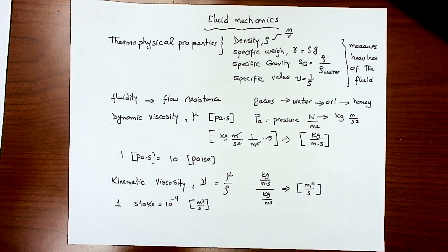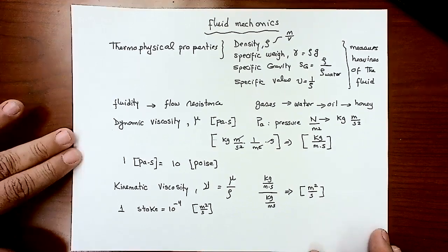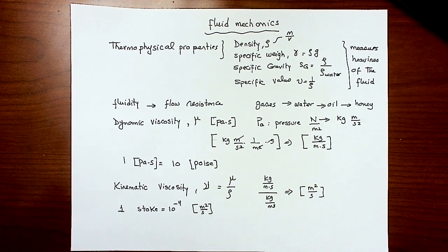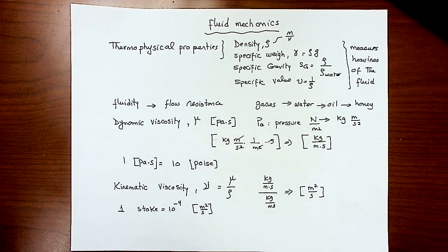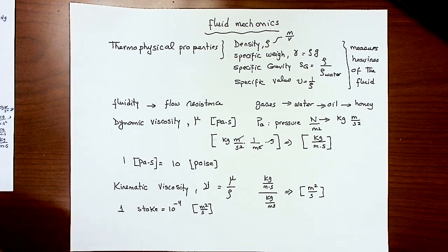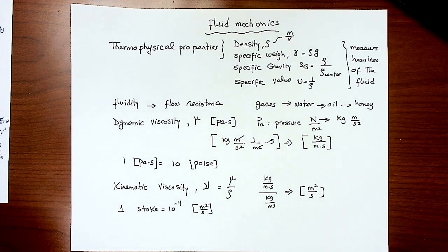Again, why do we study viscosity? Because, for example, if you are a thermal hydraulics engineer or a hydraulic engineer, and you would like to select a pump to drive liquid from one location, like a desalination station, to a living area, or you are designing a piping line in a power plant, or a pipeline to transport milk in a dairy product factory, viscosity is a crucial property you need to know. It determines the power, the pressure, and the flow rate required to drive that liquid through the pipe. That's why it is so involved in selecting equipment used in fluid mechanics. That's the importance of viscosity. So let's now imagine.